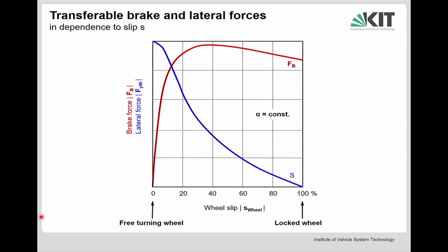One opportunity to handle this is not to allow slip all the time on all tires, but to reduce the traction force or braking force for a short while in order to let the wheels rotate free, so they will not have any slip, and then a measurement of the wheel speed can be done.